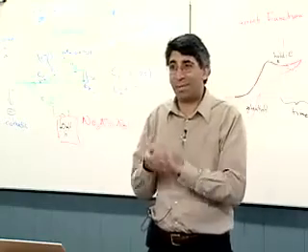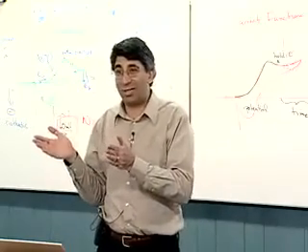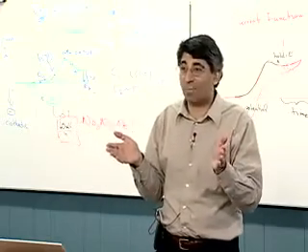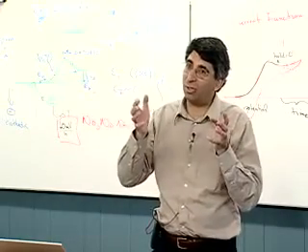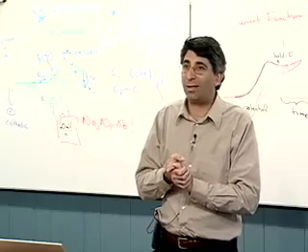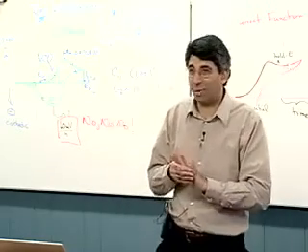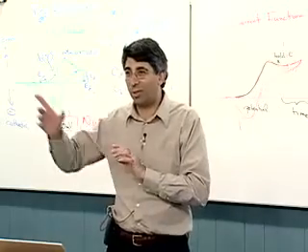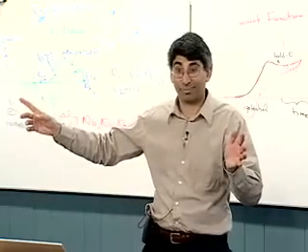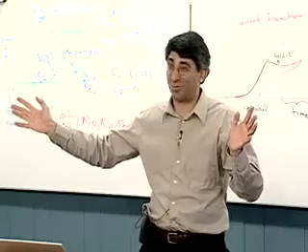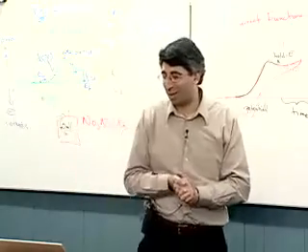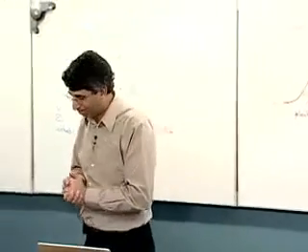So they built it. Now, ever since then, and actually before then, every other potentiostat has had an internal electrometer. Okay? And the manufacturers are just assuming that you will not put 5 miles of wire in between your reference electrode and your electrometer. But there's nothing that stops you from doing it. Okay, so keep that in mind.